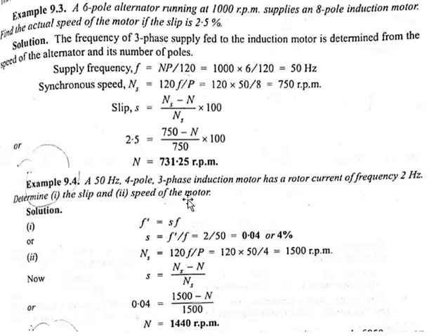Speed of the motor. In order to calculate the speed of the motor, first we have to find the synchronous speed. What is the synchronous speed? 120 f divided by p. That is 120 into 50. 50 is given, and 4, that is the number of poles, is given. We get synchronous speed as 1500 rpm.